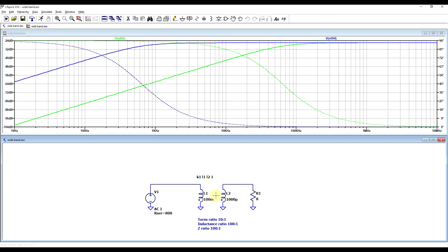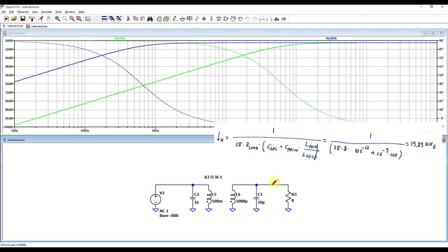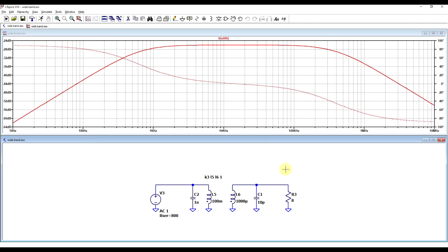Now of course, just by adding the inductance of the various inductors, we're getting the high pass effect, but we're not getting a high frequency limitation. So to do that, we also need to add some parallel capacitance. So any coil will have some parallel capacitance. And if we add these elements in, then we see the true behavior of the transformer.